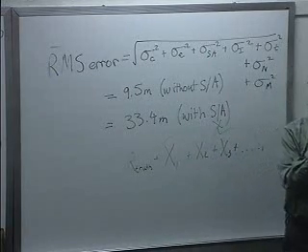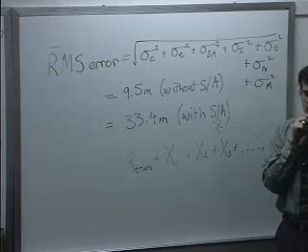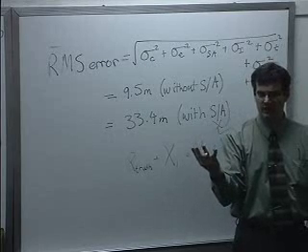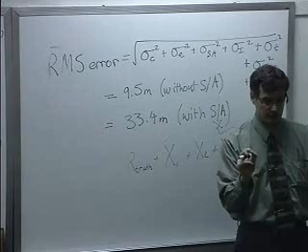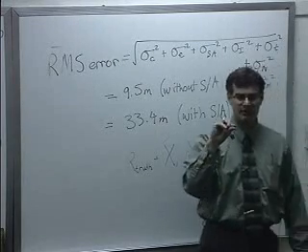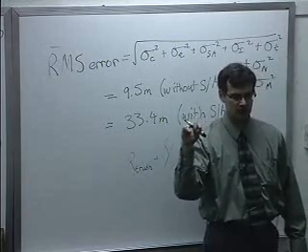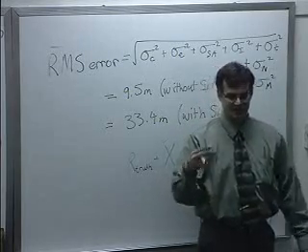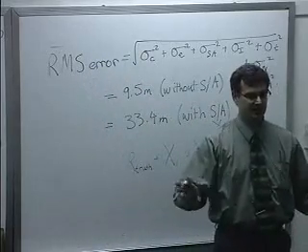Yeah, Abhishek. How are we considering these errors independent? Because the ephemeris error will affect the ionospheric delay and tropospheric delay. Or not? It shouldn't. Remember, the question is, how could these be considered to be independent errors? There may be some minute dependencies, but if you think about it, the ephemeris error is basically, oh, my satellite is just a few meters ahead or behind its course. And so the ionosphere actually doesn't change that much over that kind of region. It's sort of like if it's raining here, if I move a couple meters ahead or backwards, it's going to be raining over there too.